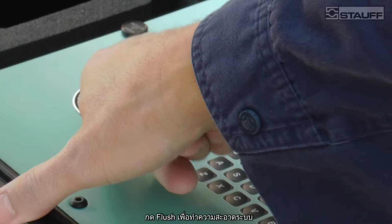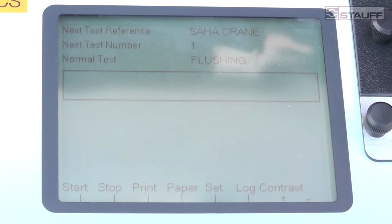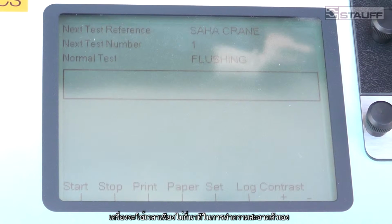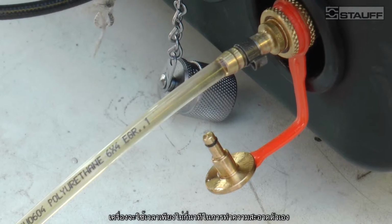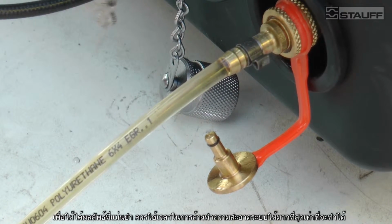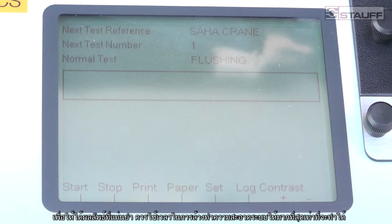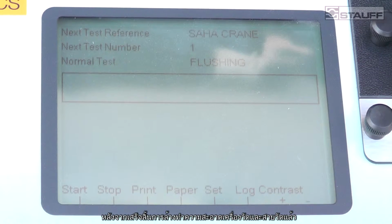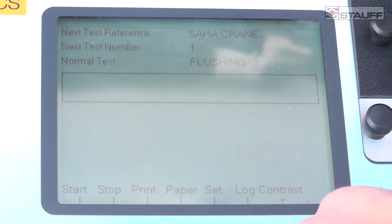Press the flush button and start flushing for a couple of minutes or seconds until you've had enough time to flush the particle counter and the hose. This is a bit longer hose than in the previous test, so make sure you give it a good flush. And now we're ready to take the test.